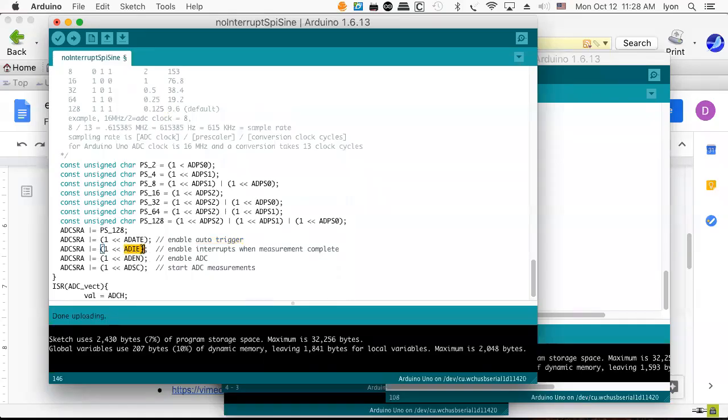Now you have to worry, oh gee, is this going to interrupt my ability to output to the DAC? The answer is no, because during that period of time, you're going to say no interrupts. If that means you lose an ADC input because you're in the middle of a non-interruptible service, you won't care that much because you'll just get it the next time around. Since it's a manual input, it's kind of okay that your stuff is interrupt driven and you'll be in the middle of something that can't be interrupted.